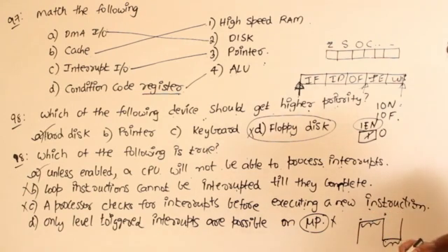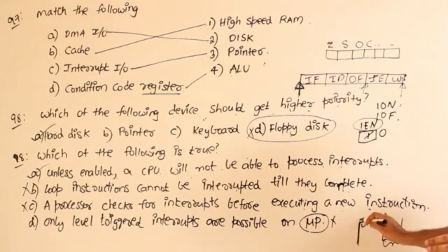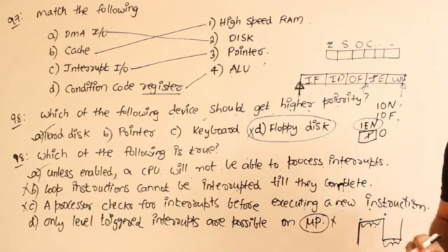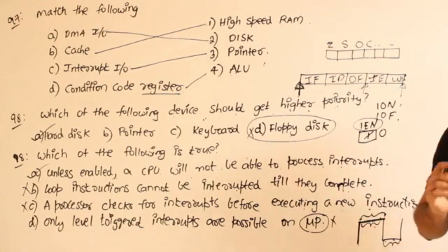So microprocessors can be configured to respond to either, but most implementations look for edge triggered only. The reason is that disturbance will be very little when you go for edge triggered, right? If you go for level triggered, the problem is that even after getting the desired value in the register, since we are allowing the register to respond throughout the time, if there is any external disturbance, there is a chance that it might again get some fluctuations.